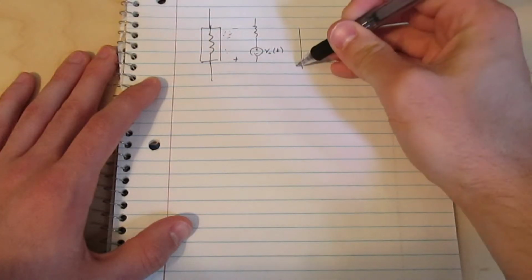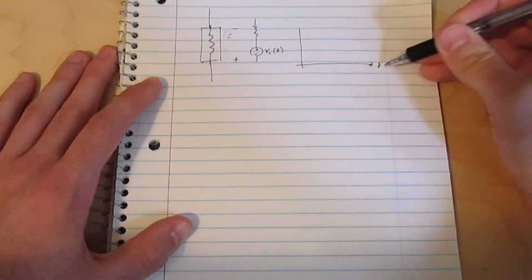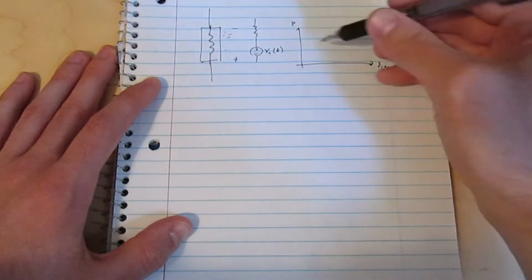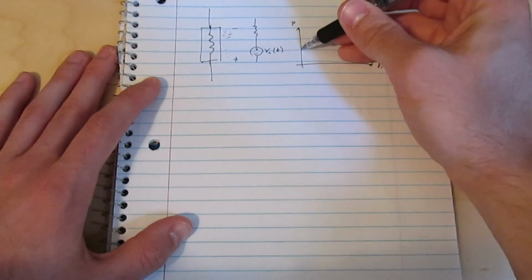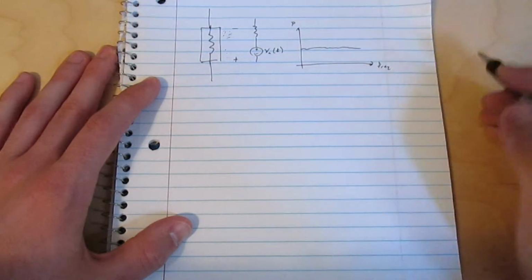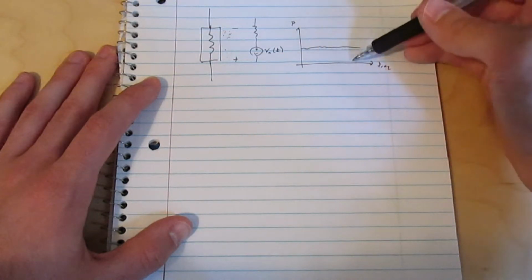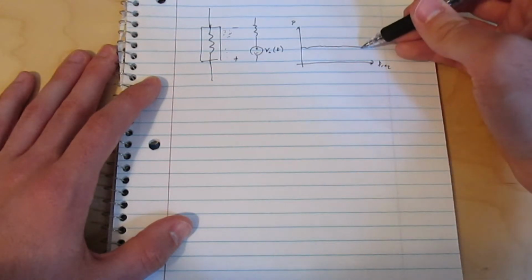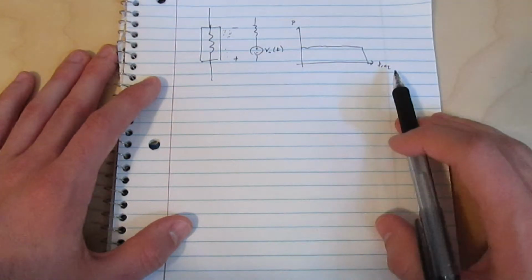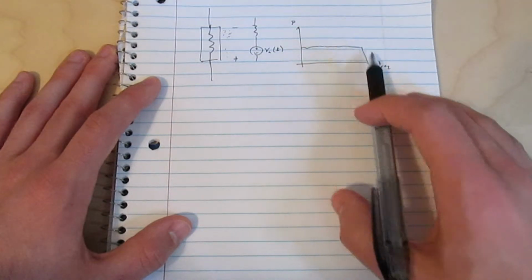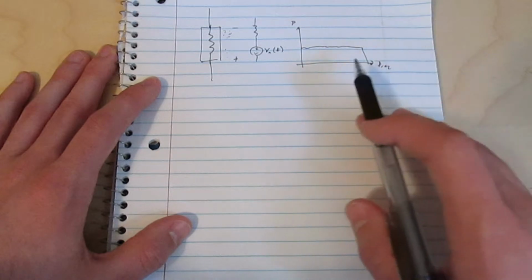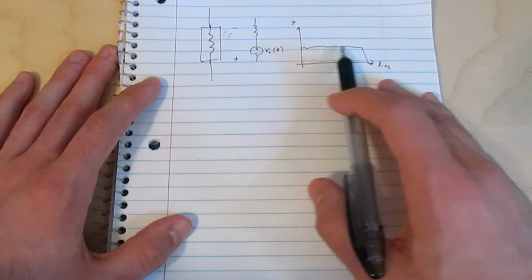And the reason it's called white noise is because it has power at every single frequency. So if you looked at the distribution of power over frequency, it's just going to be flat. So it doesn't matter what frequency you're looking at, you're always going to get the same amount of noise power. It does eventually drop off at really high frequencies, but the frequency at which it starts to drop off is way higher than anything we will ever care about. So for all intents and purposes, we can just assume it's going to be constant.